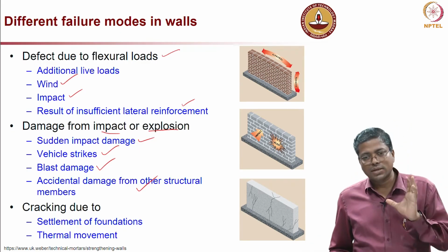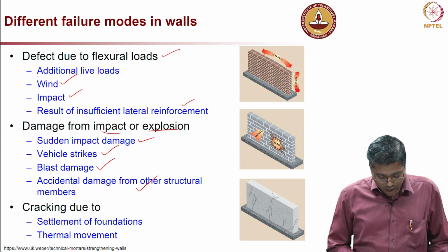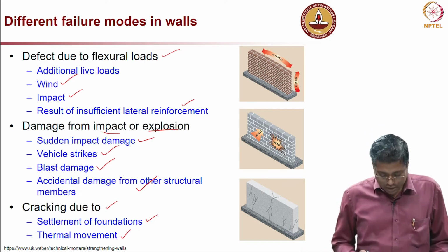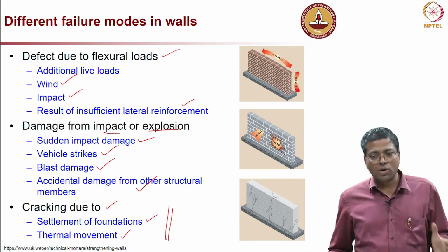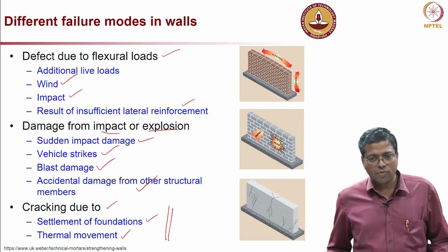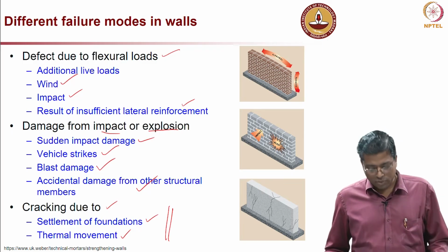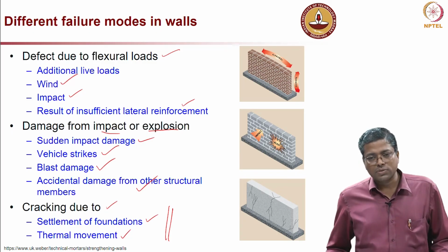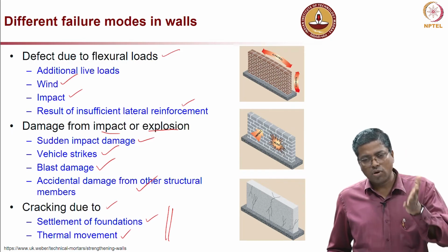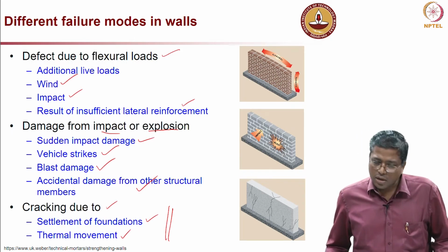Any accident, sudden loading conditions, and cracking due to settlement of foundation and thermal movement can also cause significant stress. These are very important nowadays, because we have a lot of structures with entire shear wall systems, or wall frame structures, where the entire wall system is made out of reinforced concrete.